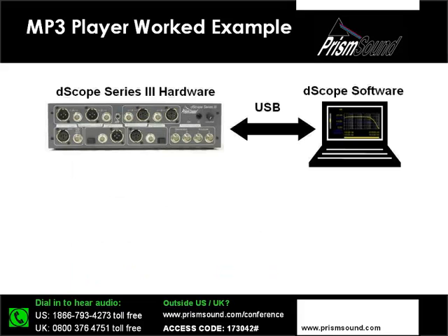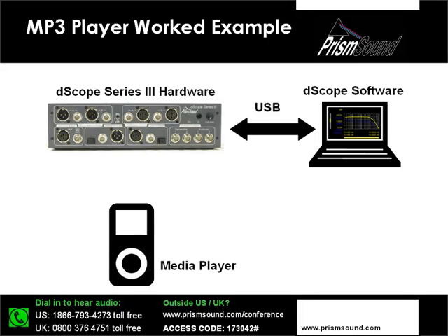So I'll just talk you through the measurement setup once again. I'm using our Dscope Series 3. I have a media player, and this media player has a multitone already saved as a file on that device. So I created the file offline using the Prism Sound multitone tools, and I've saved that file on the media player.